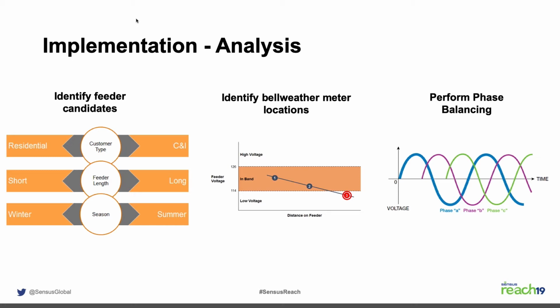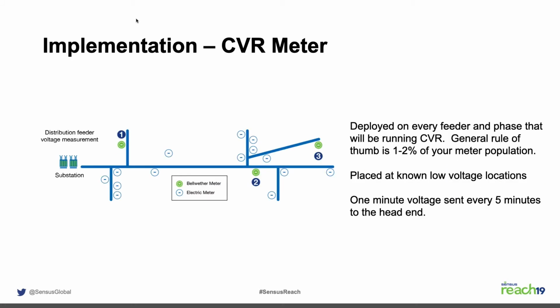So by having the proper phasing, you can associate the load to the right phase, and you can figure out, hey, I can pull this load over to this phase and get some balance, because I know the load data, and then we're set up to run this. So, food for thought with that. And then we'll dig into different implementations.